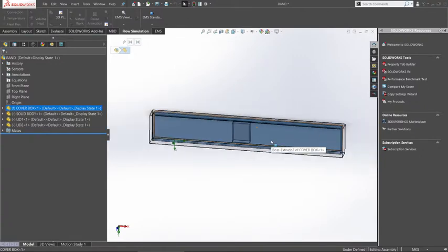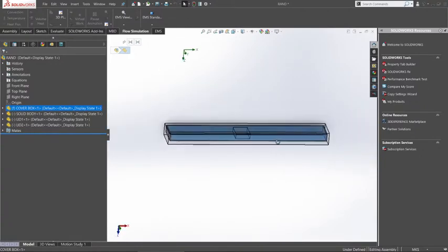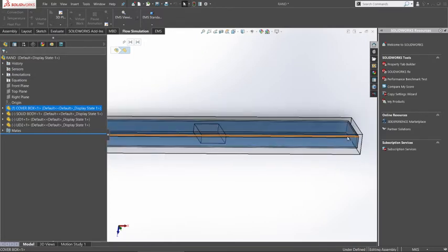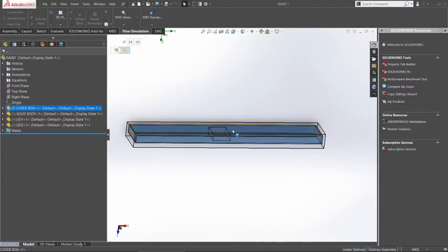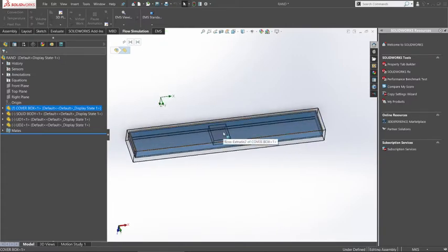But now I'll show you how I model this. This is an easy model which I've just taken as cuboidal, but you can take any part, and the same CFD can be applied to anything. If you have a polygon of 8 surfaces and you want to know the heat transfer coefficient at one surface, you can do that too.